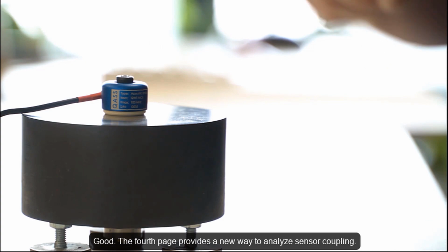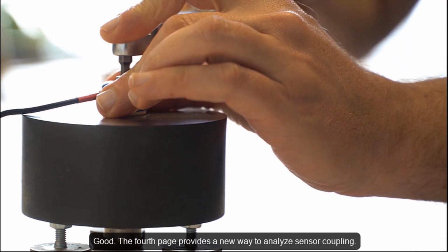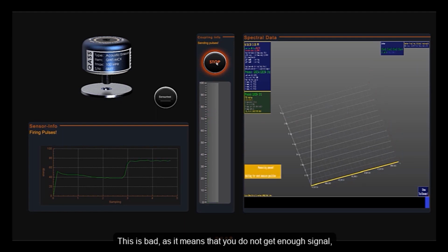The fourth page provides a new way to analyze sensor coupling. If the sensor is mounted too loosely, the energy is too low. This is bad, as it means that you do not get enough signal, and under certain circumstances you may not detect a crack.